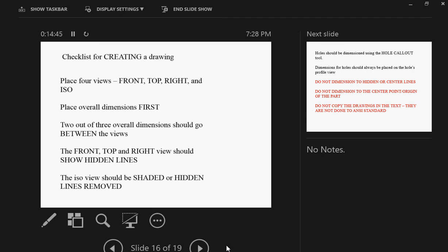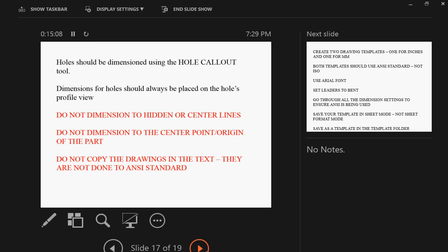Also, there's a notation for an inspection dimension. So if you want someone to absolutely check a dimension, you put it in a box. And a lot of people confuse the box with parentheses. And so now your parentheses has actually had the opposite effect of what you wanted.